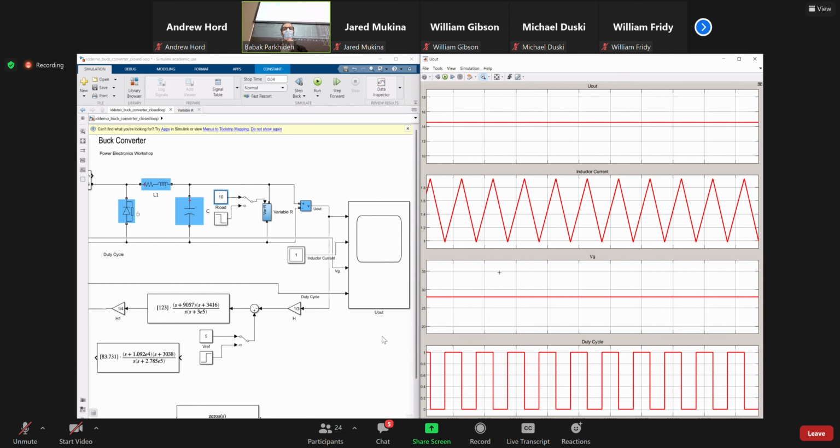Okay? Of course, if I change the switching frequency, it affects the ripple. If it's longer, it has more time, right, to go up and down, so the ripple is increased. But now we're working with a fixed frequency. Duty cycle effects. Again, longer time, I let this go, the ripple is increasing.